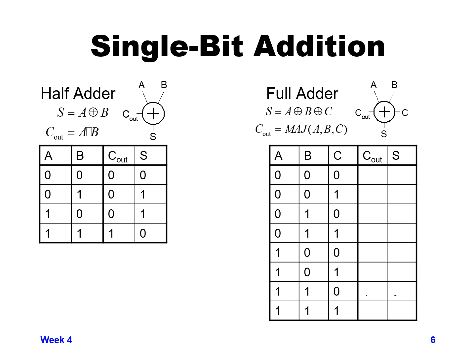And then for the carry, you only get a carry out if the majority of the 3 bits, A, B, and C, are 1. So if any 2 of them, or all 3 of them, are a 1, you'll get a 1 out. So let's look at how that resolves. If A, B, and C are all 0, your sum and your carry are both 0. If only one of them is a 1, then you should get no carry out, because you need at least 2 of them to be a 1 to get a carry out. But your sum will be a 1.